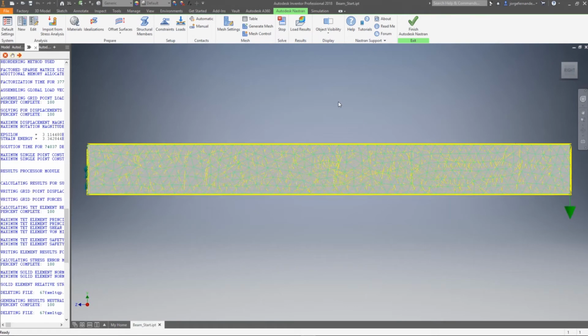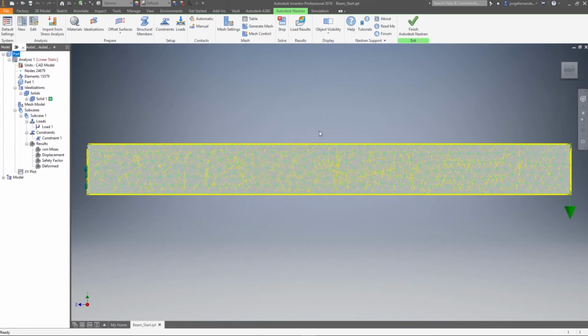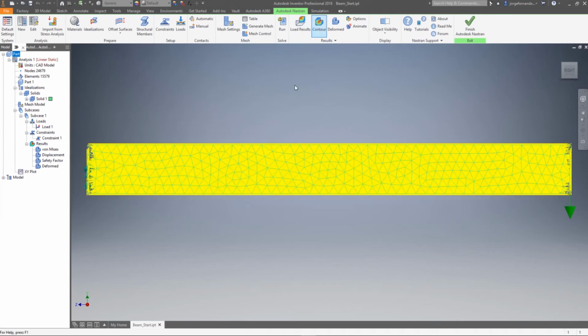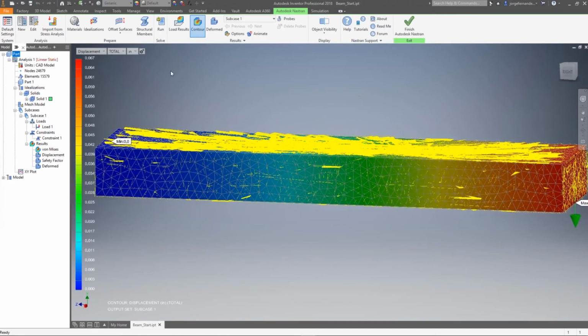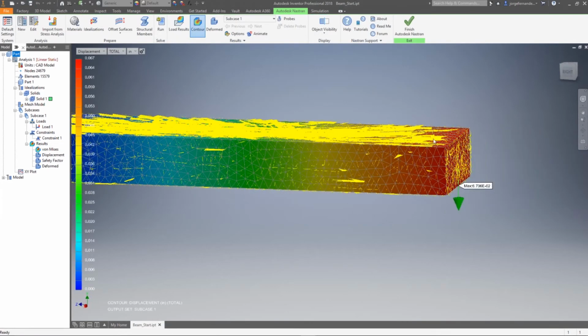Of course, for those of you that are experienced in seeing how these things react, that always helps as well, right? Right now, I just changed the mesh setting to a little bit smaller, 0.2 actually. So we're probably going to get slightly different results, but still pretty close to what we had before. Sure enough, 0.067 is what we're getting now. So as you see here, as I tightened up the mesh, we're going to get better results in this case.